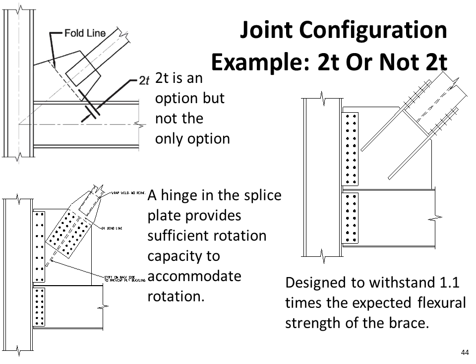If as the engineer of record you're delegating connection design, but the only thing you're going to accept is the 2T on the brace, then you should make that very clear that that's what the requirement's going to be. Otherwise, the fabricator or the contractor should be free to choose whatever is going to be most economical for their work.